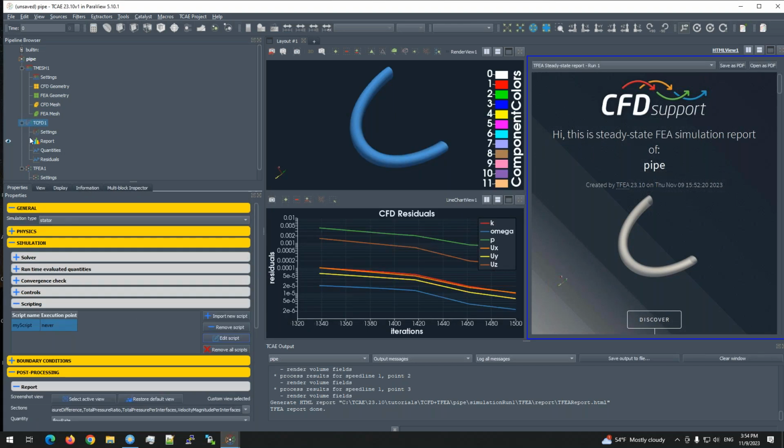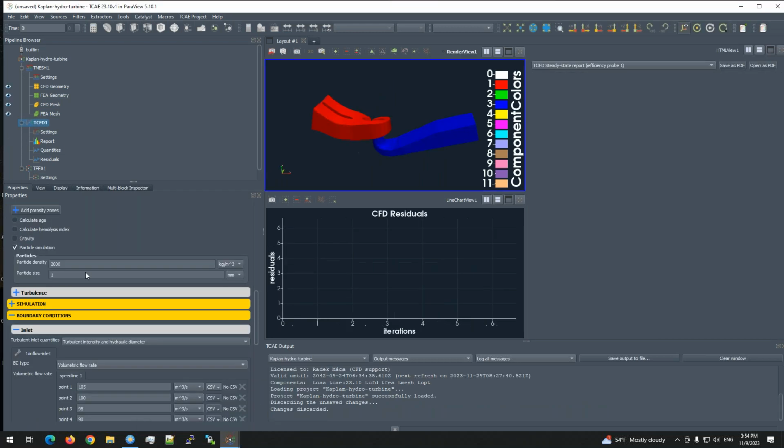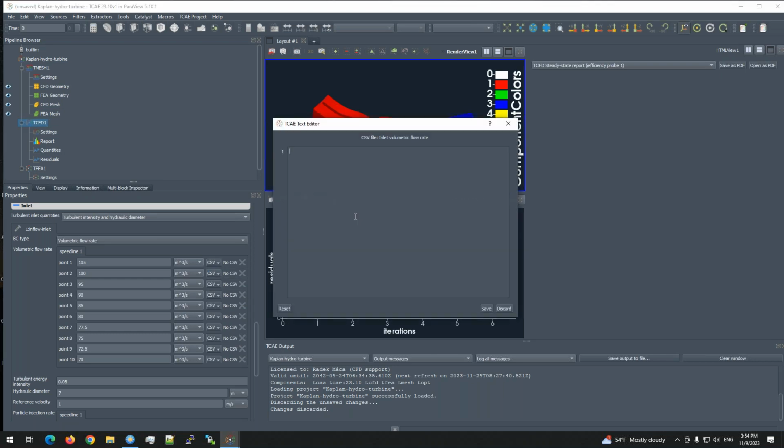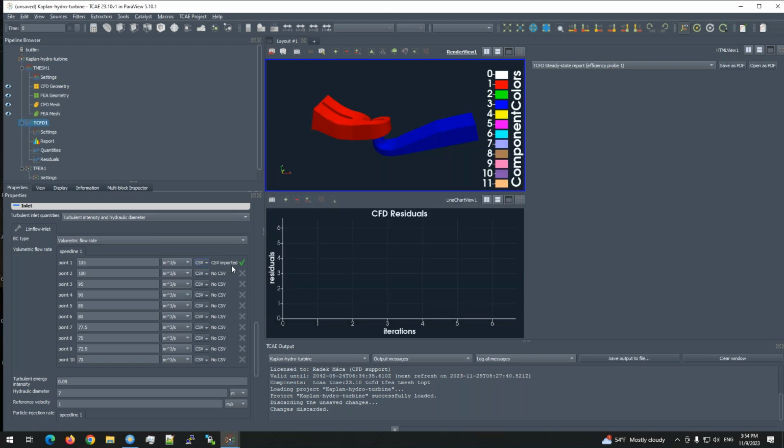And this also holds for boundary conditions. You can create new ones or import them. You can create new boundary conditions, defining some format, time, and value. So you can do something like this and import a time-varying boundary condition for volumetric flow rate, for example.